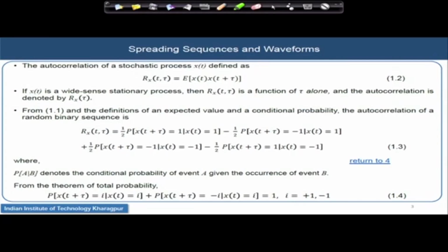It is really hard in practice to design a code where the autocorrelation property and the cross correlation property are simultaneously good. I mean to say, the autocorrelation property is very high, perfectly nice, with very low power in the side lobes, and simultaneously the cross correlation is really very low, close to 0 values. Getting such a code is really hard in practice. We will see later on, either you will get a code having very good autocorrelation property and very less cross correlation, or vice versa.